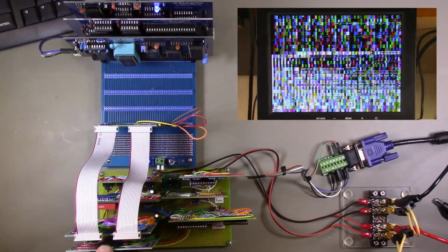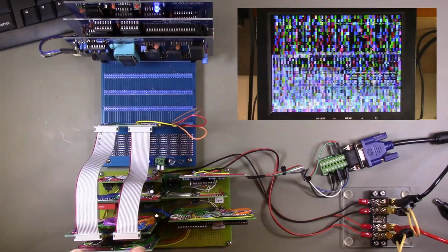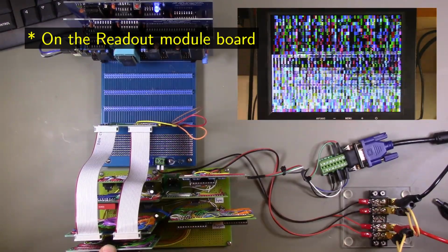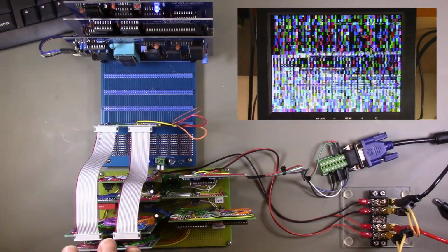I think the problem is that this readout module has some long wires, it has no ground plane, it's kind of a worst case scenario for signal integrity. So I think what we potentially need to use is parts that aren't as prone to creating these voltage spikes. And the thing that I tried first was to use 74ALS163 counters on this board. And my hope was, cross fingers, that will eliminate the ground bounce issues that I think are causing these glitches.